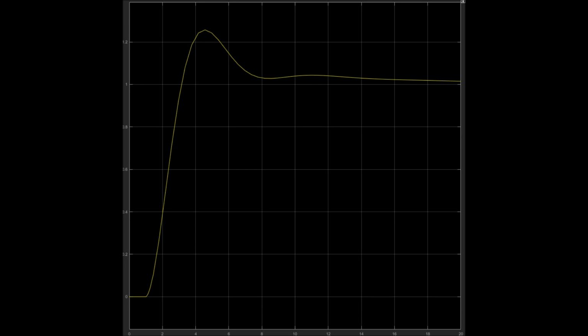It is also important to note that for our transient response time, we were evaluating with the step response and with the settling time. And the settling time at 20 seconds was only 1.5% above the target input, and so that's very, very close. It's not as if it was off by 10%. So depending on your definition of settling time, it may have been an acceptable parameter.